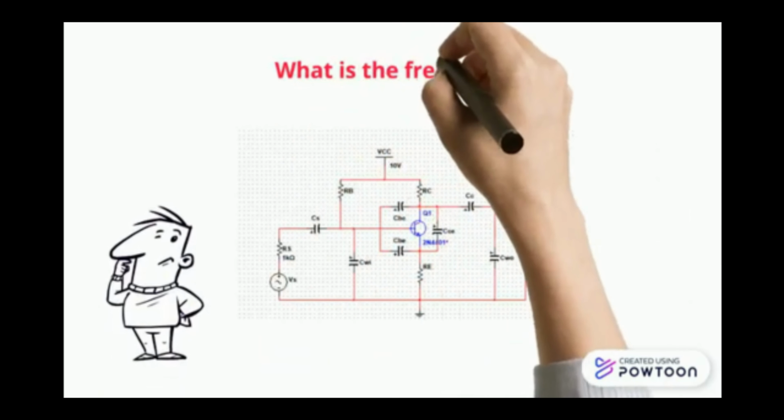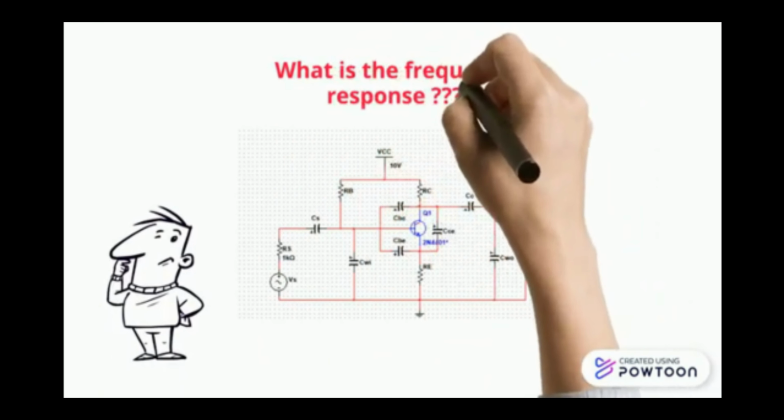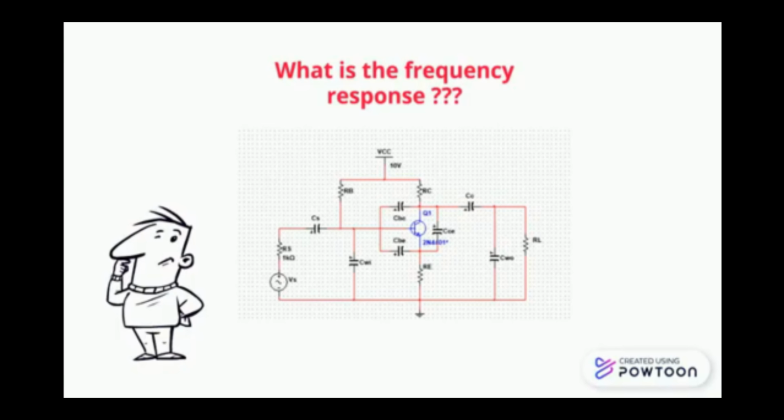What is the frequency response? Frequency response of an electric or electronic circuit allows us to see exactly how the output gain, known as the magnitude response, and the phase, known as the phase response, change at a particular single frequency, or over a whole range of different frequencies from 0 Hz DC to many thousands of megahertz, depending upon the design characteristics of the circuit.